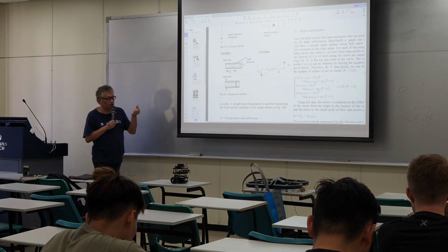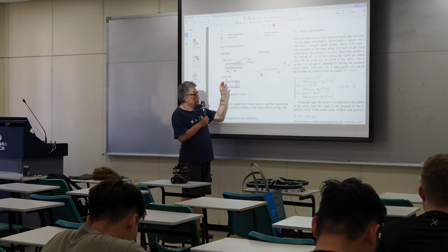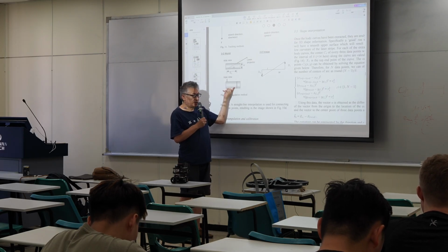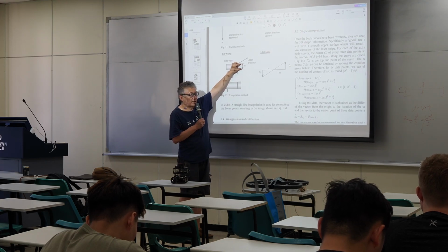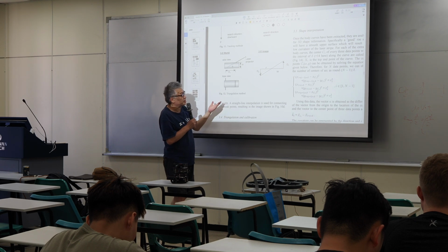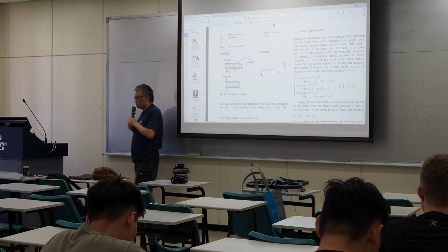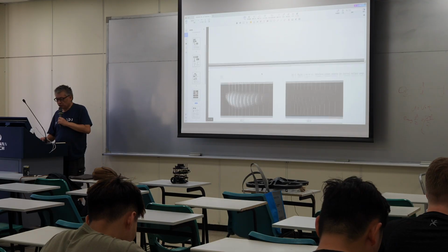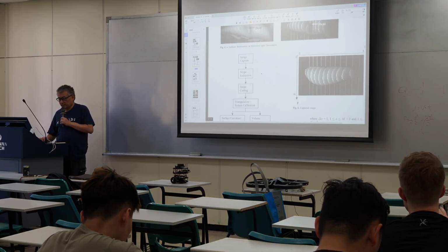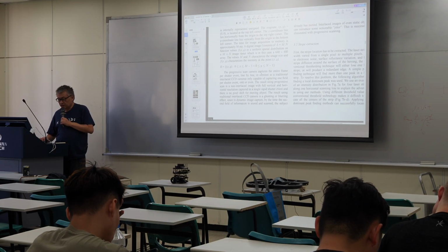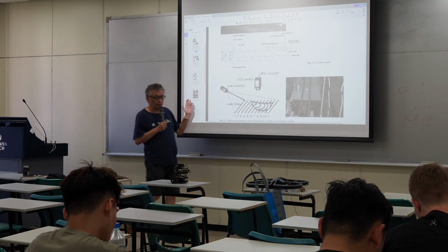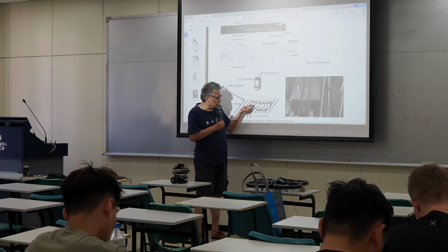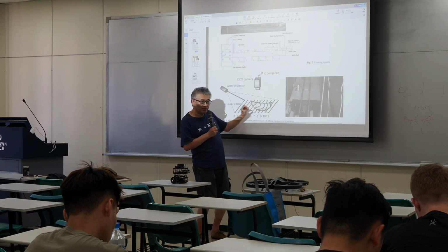Okay. The shift of the stripe in the image is proportional to the height of the obstacle, of the object. That's it. That's the RGBD. So the measurement, that's why it says RGBD, and the depth is measured by the structured light. Project a laser light stripe, so it will shift in the image. So this shift is proportional to the height.